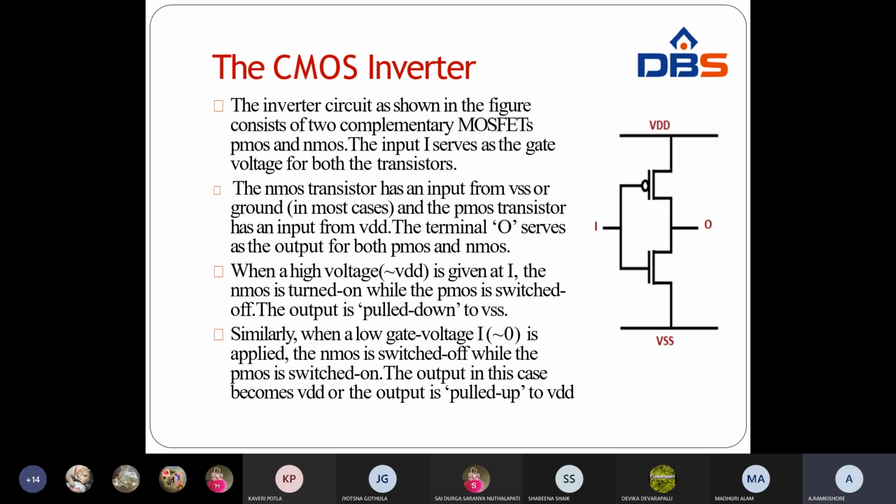So the channel will not be formed within the device from source to drain, and the device does not introduce VDS voltage. Irrespective of VDS and the channel, the device doesn't operate. That means current does not flow through that device, so the PMOS transistor will act like an open switch.